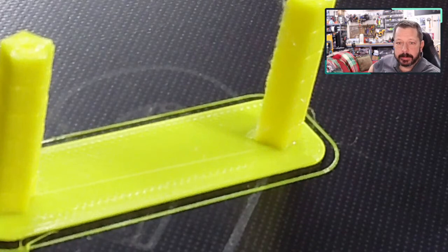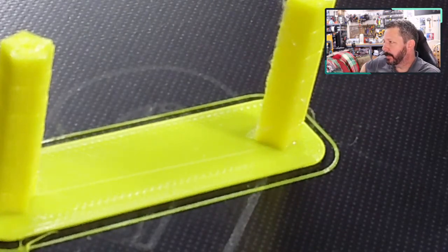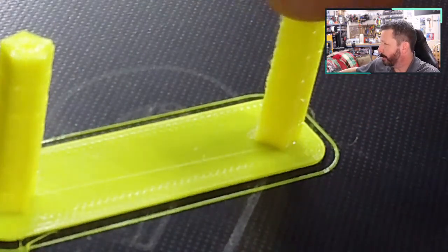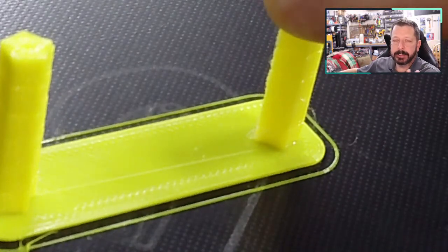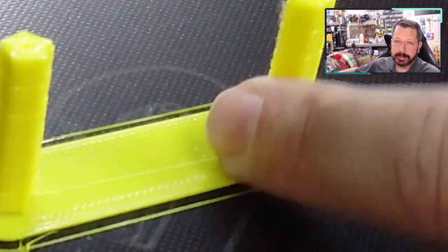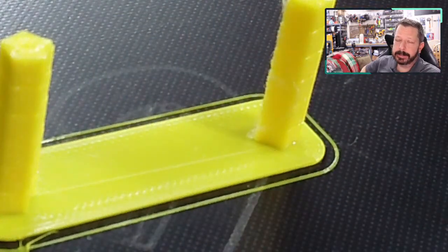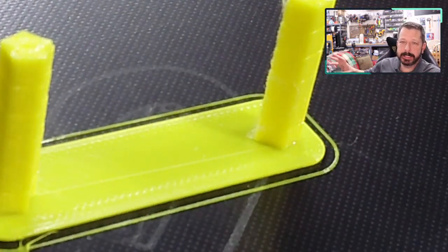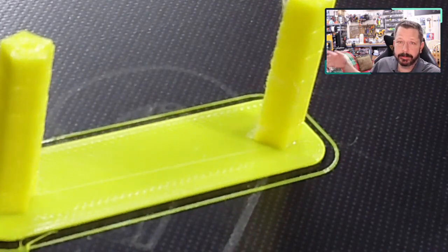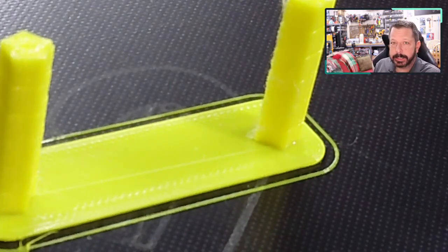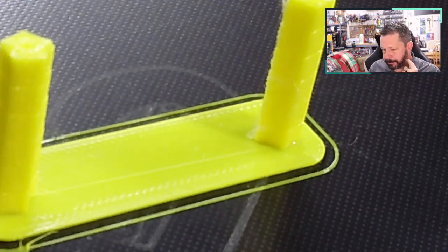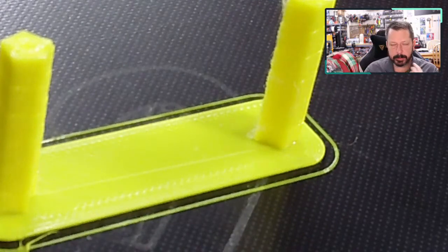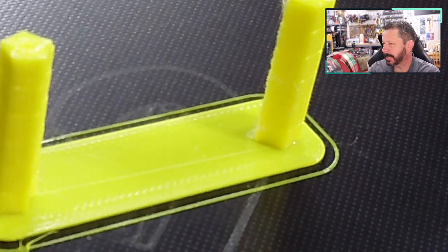So I'll print another one. It doesn't seem like retraction distance makes too much difference. They did seem to get better, but I don't want to go too high, so I'm going to print another one by changing retraction speed and see what the best result is there, and then I'll take a combination of distance and speed and print a third one and see if we can get tuned in to what our best retraction settings are going to be. All right, we're not going to be able to print another one of those today. We'll run out of time.